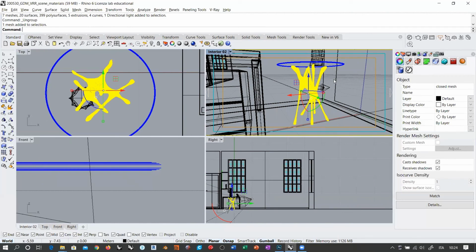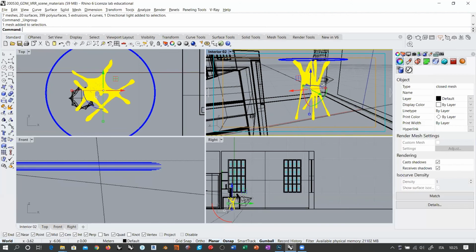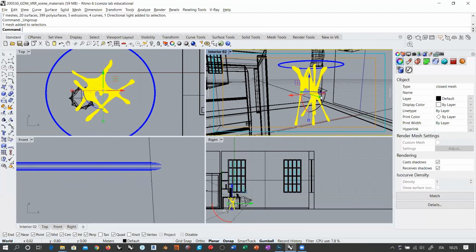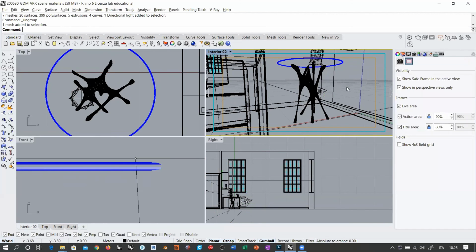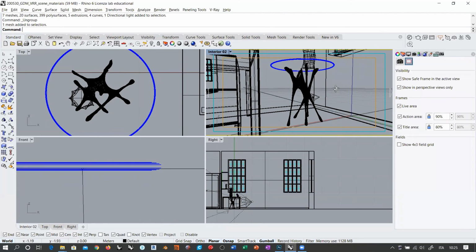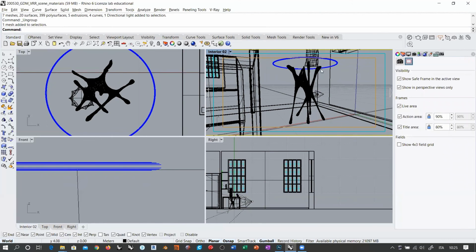But if you work with another software, which could be any polygonal modeler like Blender, Max, or anyone, you can. For example, the process normally consists in a pass which is called Retopo, where you take the high resolution mesh and create a lower resolution version of this thing, controlling the polygon position and shape all over the surface.